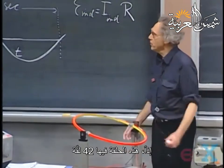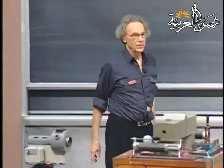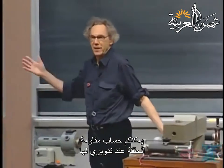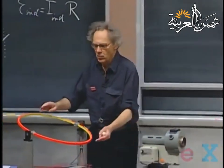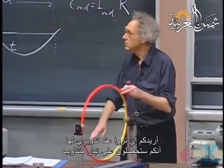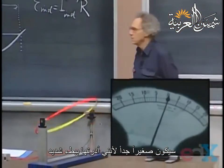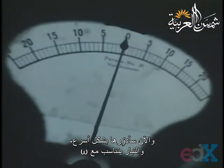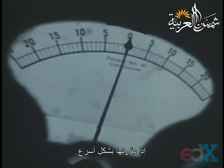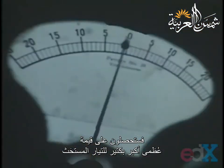So here is that loop, 42 windings. The scale there is in microamperes. So if you want to, you can calculate what the resistance of the loop is when I rotate, but that's really not my objective. I want you to see that when I rotate it, you get an alternating current. Very modest, because I rotate very slowly. Now I rotate faster. It is proportional to omega. And so if I rotate faster, you get a much larger maximum induced current.